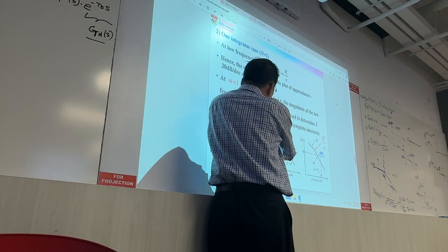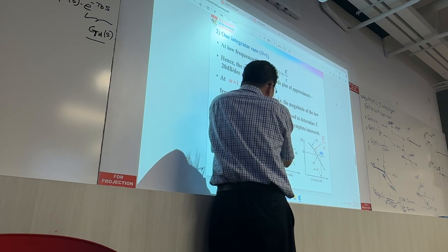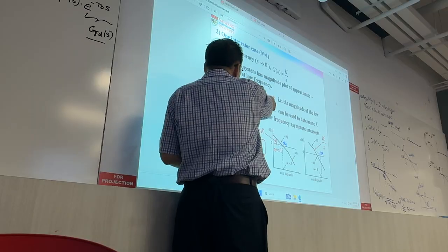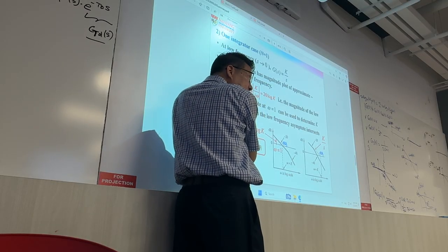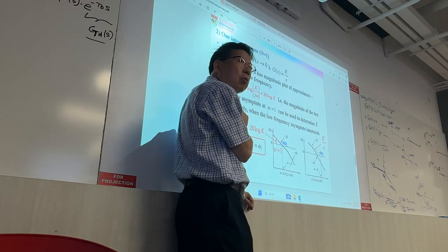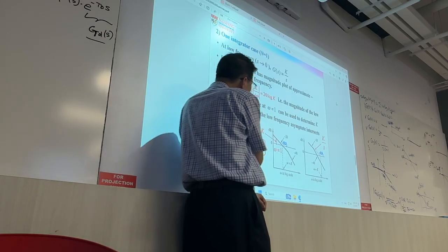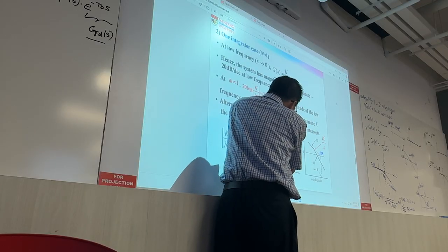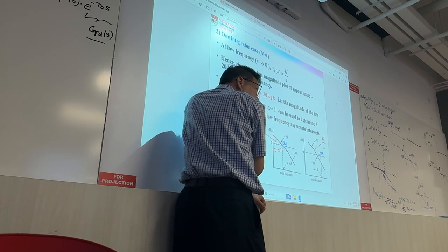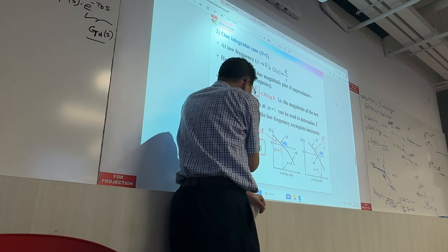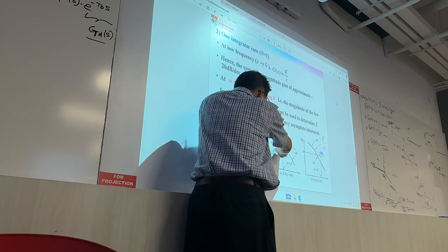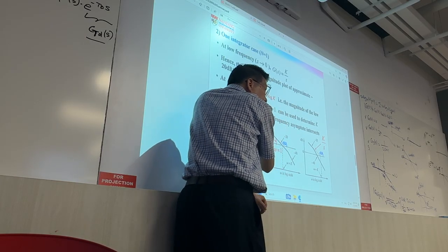At this frequency 1, this value is 20 log K. Okay. The other case is when this ratio is equal to 1, then the whole thing is equal to 0 decibel. Correct? So that means at 0 decibel, this ratio is equal to 1. That means actually this crossing frequency is equal to the value K.